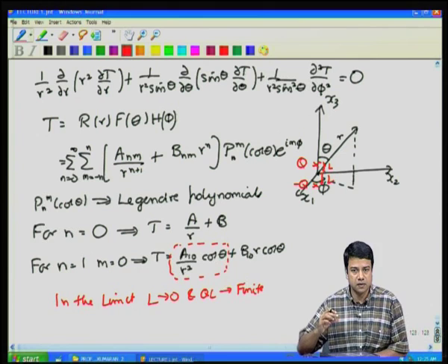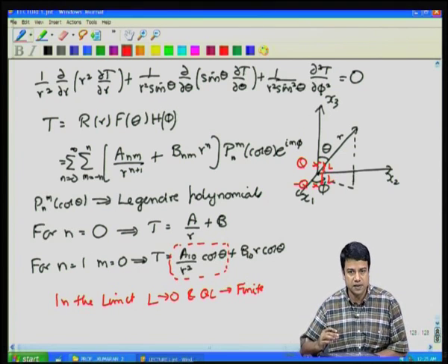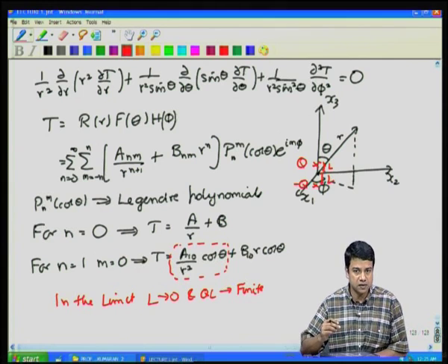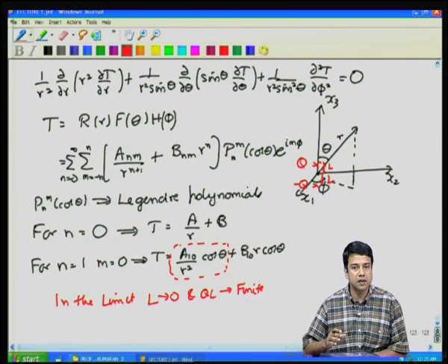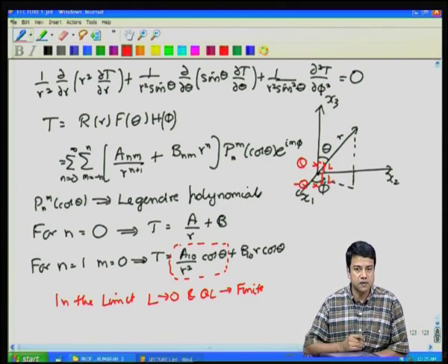If it is separated along the plus and minus z axis, a small distance from the origin, in such a way that the distance goes to 0, but the source strength or the sink strength times that distance remains finite, you get this second term. There is no net source. So, therefore, the contribution proportional to 1 over r is equal to 0, but you get a net source and a sink, and that gives you this term, this dipole moment, the source and sink of heat separated by a small distance.